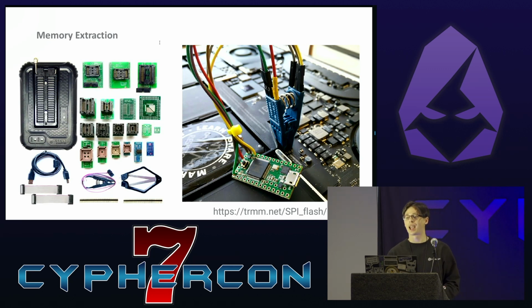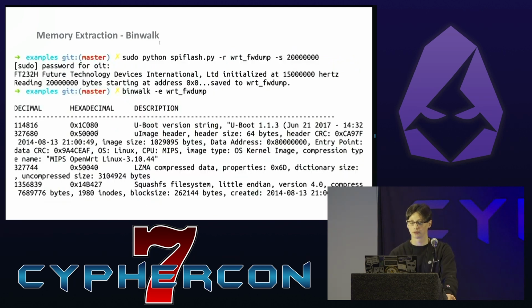One of the problems is as you try to power up the memory chip to try to read from it, that can also power up enough other systems on the board that start trying to read the flash, and then it's busy when we're trying to talk to it. So sometimes you do have to take the chip off the board, and something like a T48 programmer on the left here supports tons of chips. It's very fast, great option for working with a number of different memory formats.